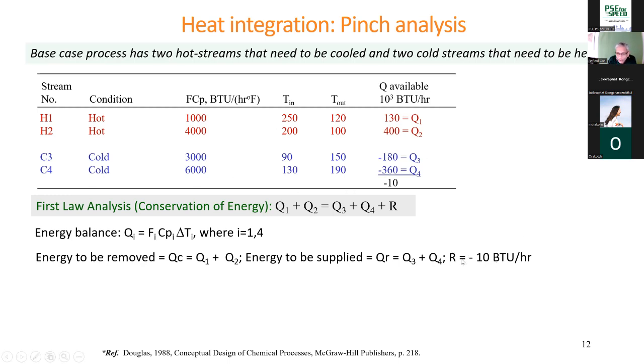So then the question is, if we integrate the hot streams with the cold streams, and if we can do that, then instead of adding all of this energy and removing all of this, we only have to add this amount. So heat integration can save a lot of energy.